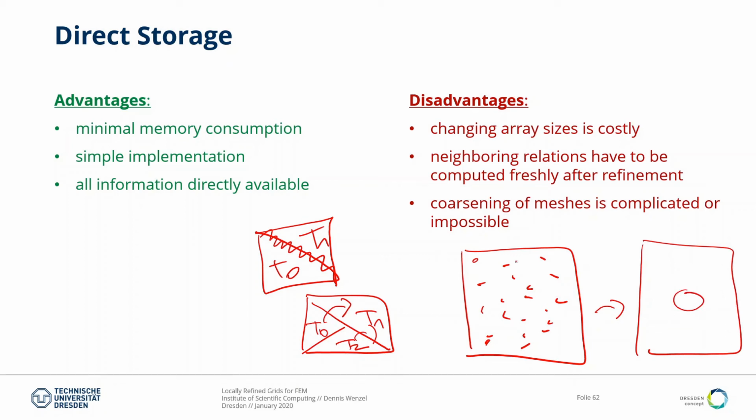So in the beginning, you would need to use fine grids around all of those drops. But of course, over time, you want to coarsen them because you don't want to have residuals of this fine grid after a long time, when you only have constant -1. So coarsening is an important task.